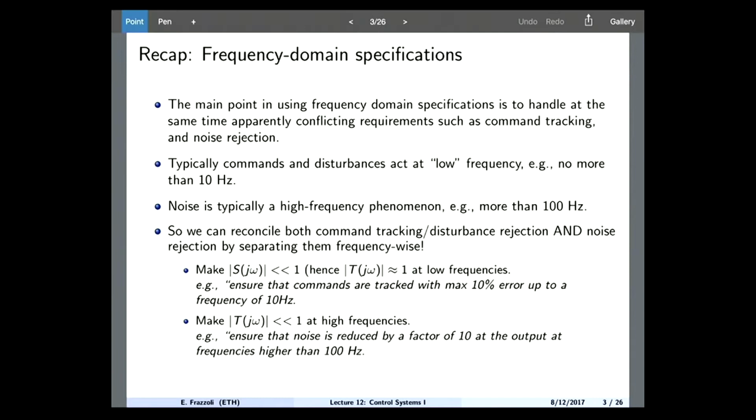On one hand, you want your control system to be stable, and to follow commands quickly. But you also want it to be robust, not sensitive to noise. How do you distinguish between a command and noise? Commands are low frequency, noise is high frequency. Unless you get into the habit of thinking in the frequency domain, it's very difficult to make this distinction.